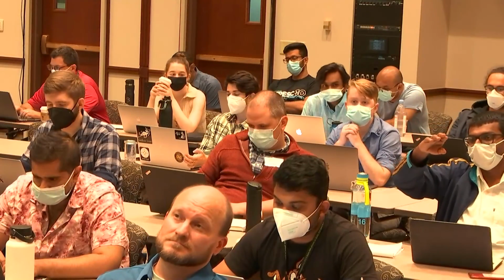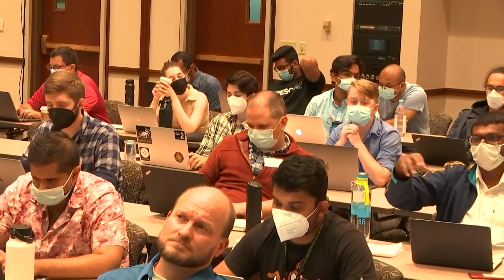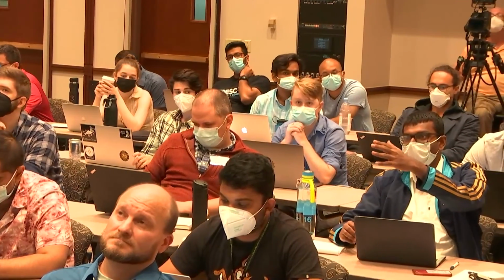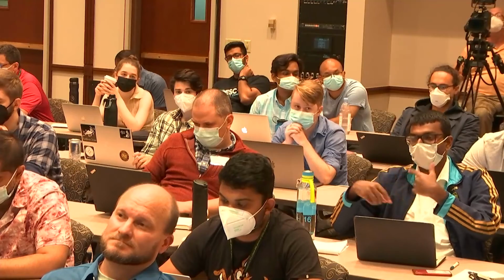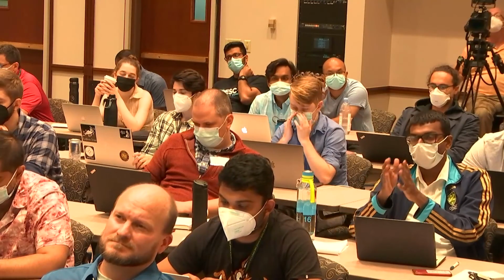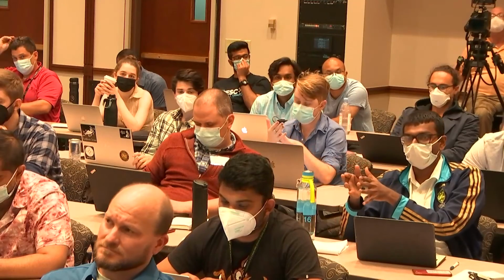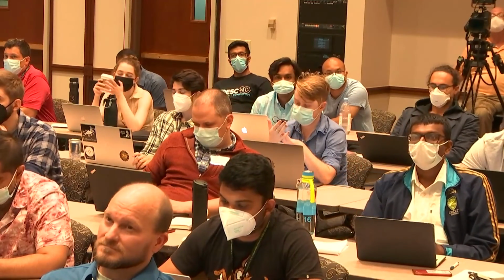So when it comes to a reaction, diffusion, convection process, it's going to be very stiff, right? So would SUNDIALS basically carry out more tests to hone in on the right time step, or is some sort of sub-stepping also possible? So in this case that we're looking at right now, it's going to pick the time step based on the requirement of the fastest time scale.